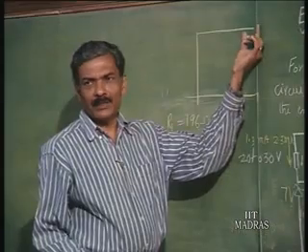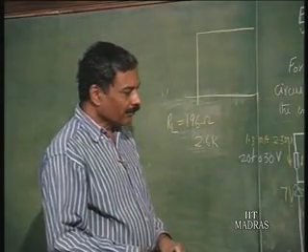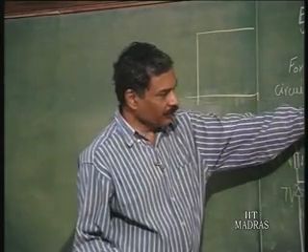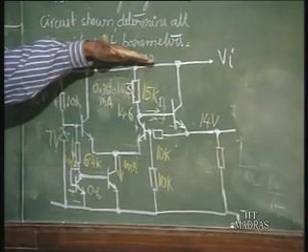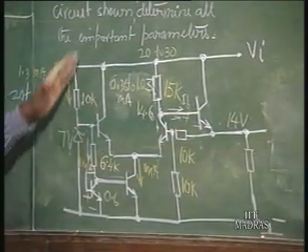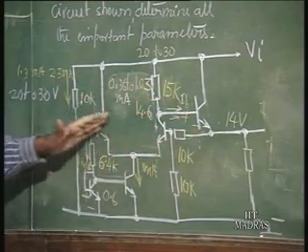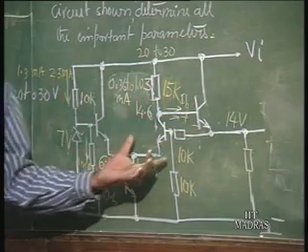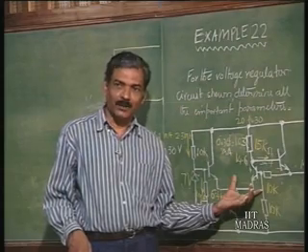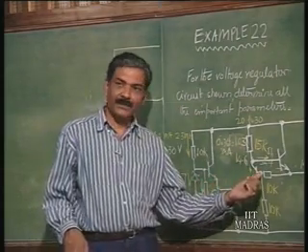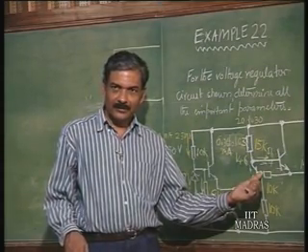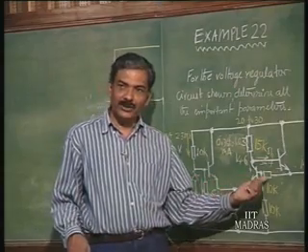This may be a very small variation. If the input voltage is kept constant, this variation is going to occur because of the non-idealities of this differential amplifier that we have, and that is going to be extremely small. We are assuming that the voltage difference is 0, it is not strictly 0. So the error voltage is 0 is what is assumed.